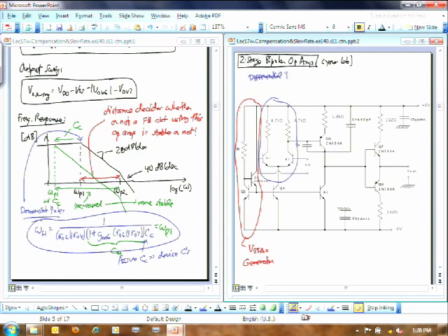And then I can look at the bottom of this thing here. If that thing to the left is a V-bias generator, this thing right here is a current source. Okay? So that single current source is supplying the op-amp differential pair tail current.